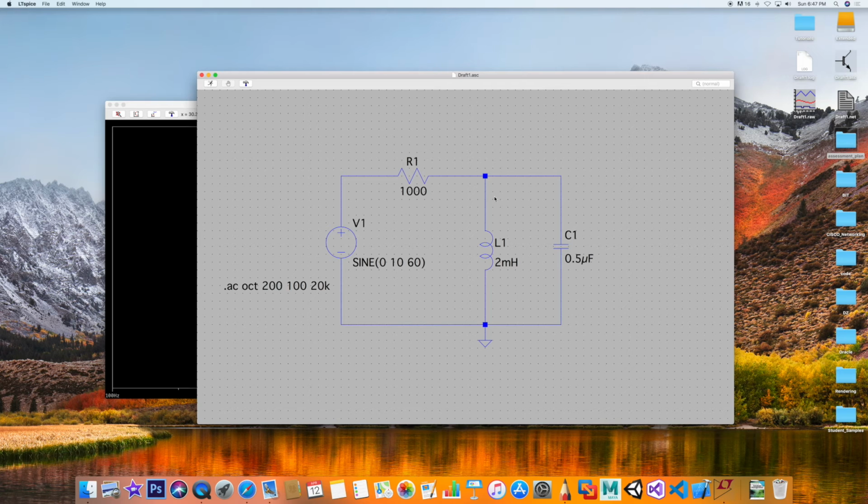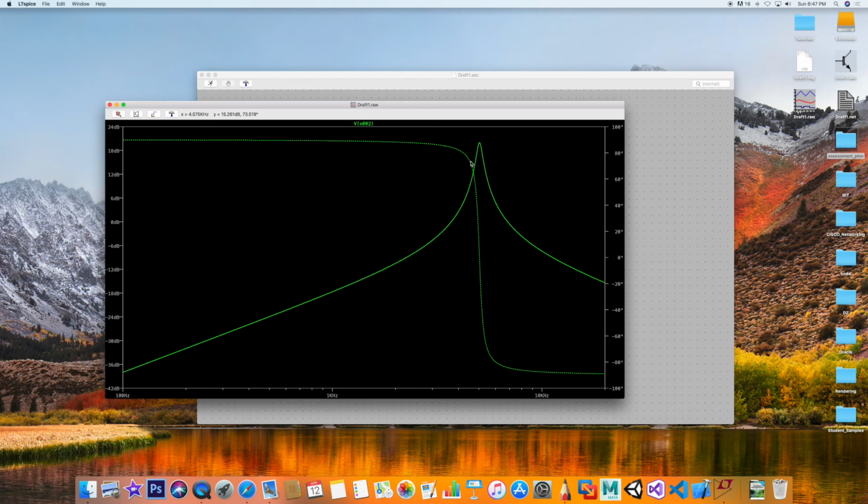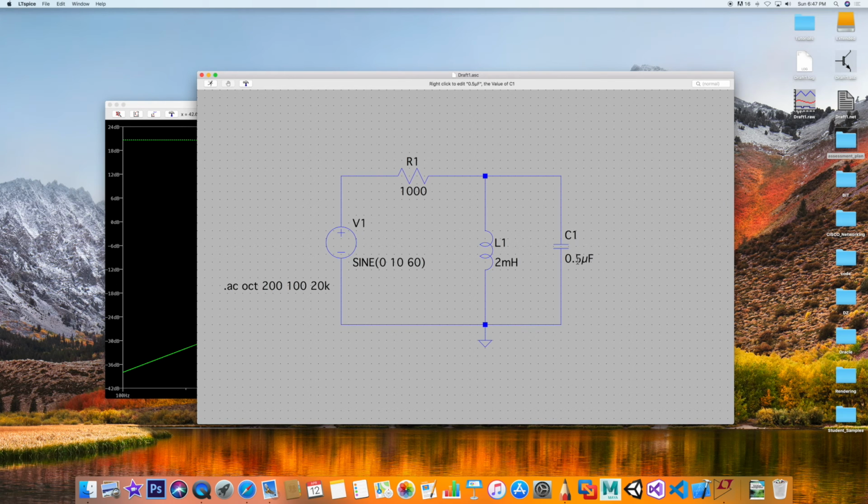So let's click here, and notice now we would have a shift to this side. And where is that at? Notice now we're at 5 kilohertz, right? So we've shifted dramatically towards a more capacitive circuit here. What if you did even more? Let's say we went down to 0.05. Now, those are dramatic changes. I'm doing these by factors of 10.